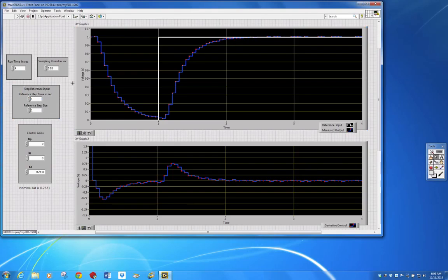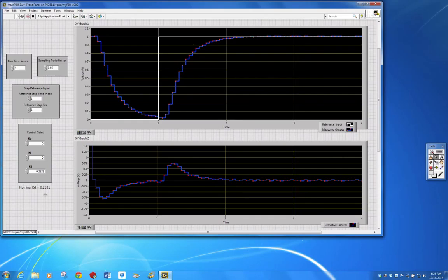Hopefully you recall that we're dealing with an analog plant here that has a lightly damped vibration mode at approximately 1 Hertz, and that in turn dictates an absolute minimum sampling rate for controlling that vibration mode of 2 samples per second. So here we're looking at some results where we've sought to control that vibration mode using a sampling rate that's 10 times that fast, or 20 samples per second. But we've got a really nice opportunity here to explore the use of slower sampling rates. So next, I want to quickly do exactly that.